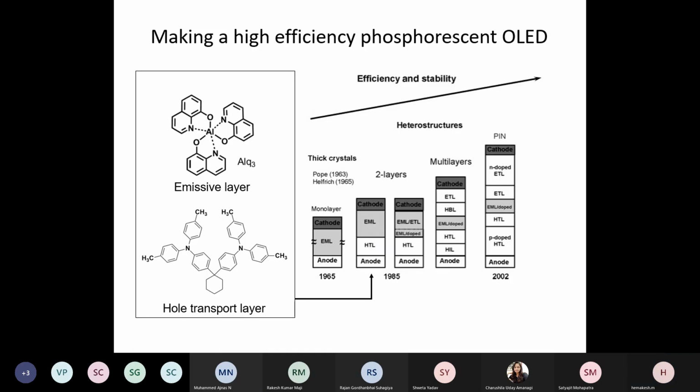In those complicated devices, you have things like hole transport layer, p-doped hole transport layer, electron mobility controlling layers, electron transport layers, doped electron transport layers. So many small variations in different kinds of material that you can layer in and control the thickness of the layers as well, to have more and more efficient usage of the electrical energy to generate light.